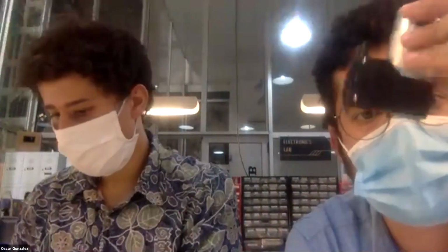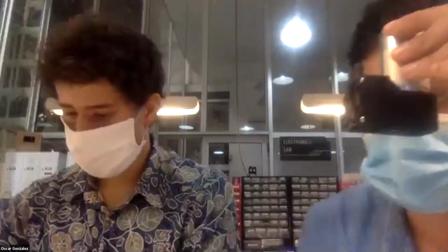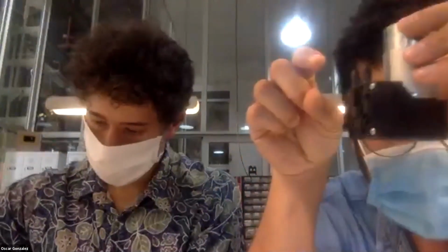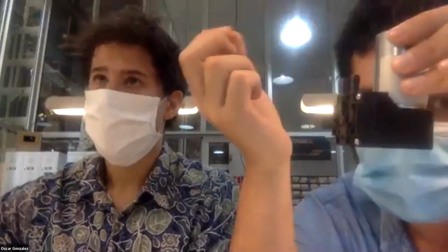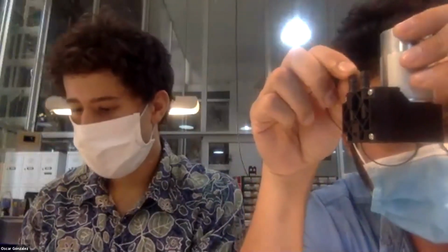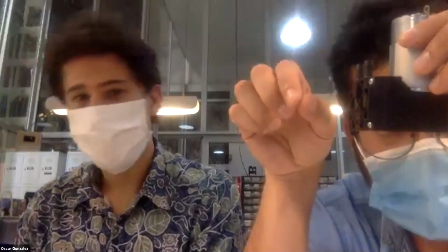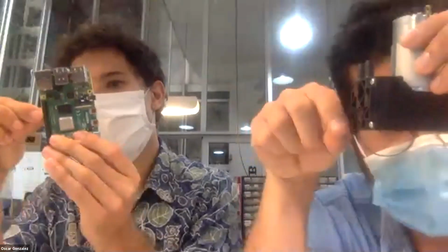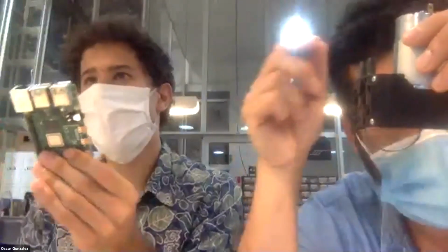Oh, okay. I just want to ask, do you think the pick and place machine would be hard for this assignment? No, actually, it's really similar to the paste extrusion. This pump can make pressure and vacuum. The vacuum amount I can make is small, but usually what you do is use a small needle or really small syringe system, and you use the vacuum from the pump to release. Actually, you will need one of these pumps and a small air valve solenoid to release the air and differentiate which circuit you are taking the air from. But the pick and place will be really nice, actually.